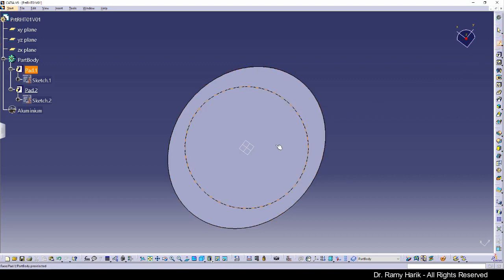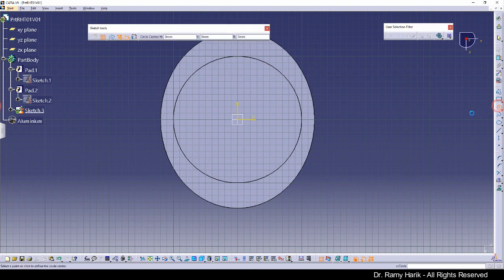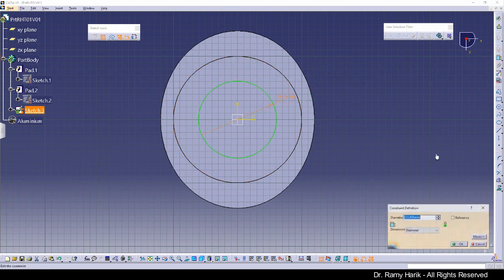and then we're going to click on a sketch on this part, and the sketch is going to be, as described on page 11, a 30 millimeter circle radius. As we did before, I'm going to create a circle, click on constraints, and double click that value of the constraint and put it at 30 millimeter radius. So you can select radius and you can put 30 millimeters.